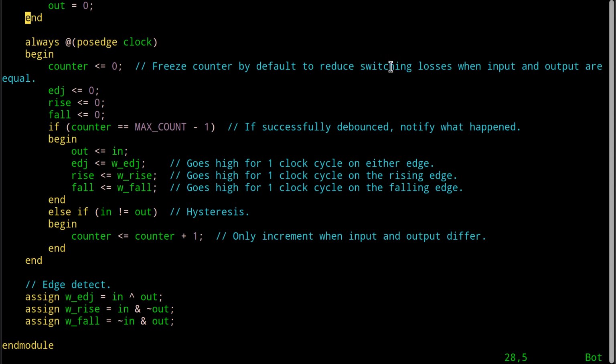That is the best way to cut your power consumption, let's say on an existing silicon die design, okay? And this is why all these microcontrollers and system on chips and stuff like that have these horrifically complicated and unbelievably annoying, in many cases, phase lock loops and clock system generators and multiple speed clocks for high speed and low speed and all this crazy stuff. And the reason they do that is for battery powered circuits and stuff like that. Sorry, again, another digression, but that's what they're referring to here. And that's, like I said, a pretty good idea.